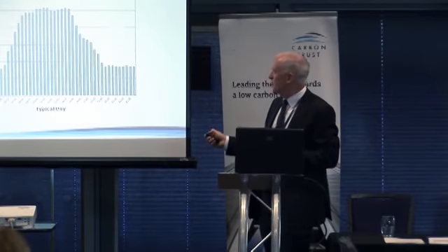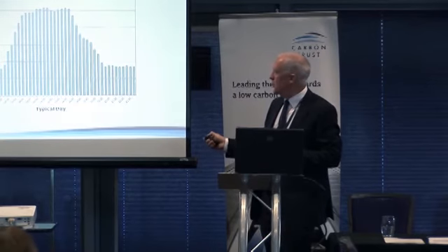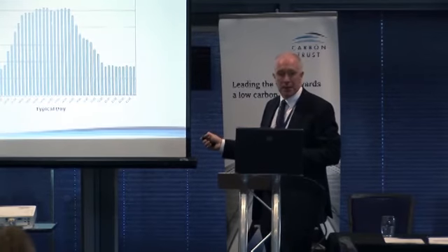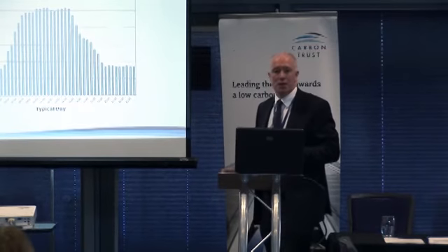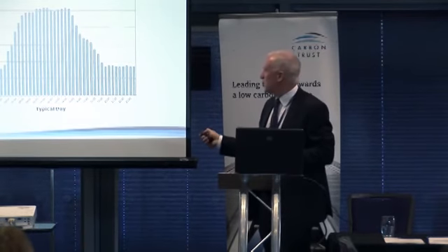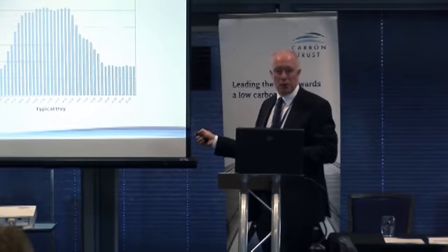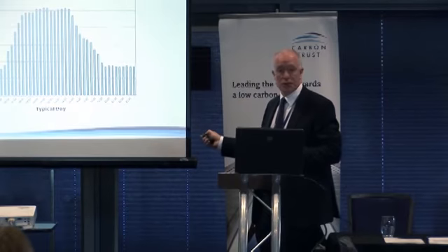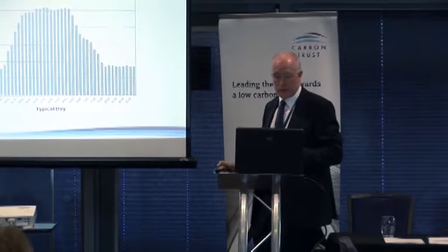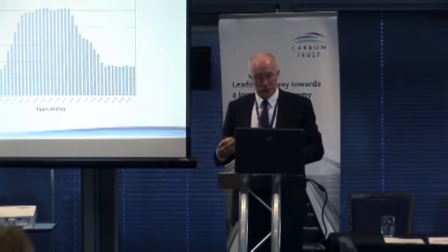And this is the profile of an office. You've got the start-up, full occupancy, and then people at the end of the day going home, and the building completely vacates at about 8 o'clock, and you've got this typical line. There'd be a few people in the office, but an awful lot of plant and lighting left on at the end of the day, because people aren't switching things off and the kit's left running because people haven't shut off the plant at the rooftop, etc. And that's a sort of typical waste.